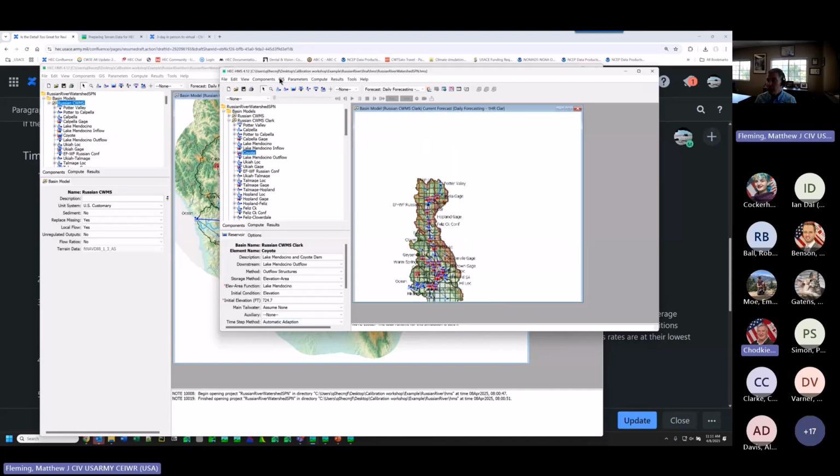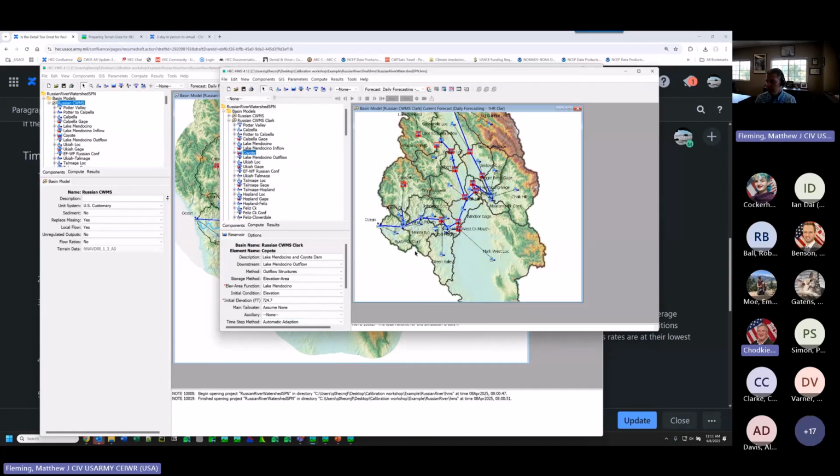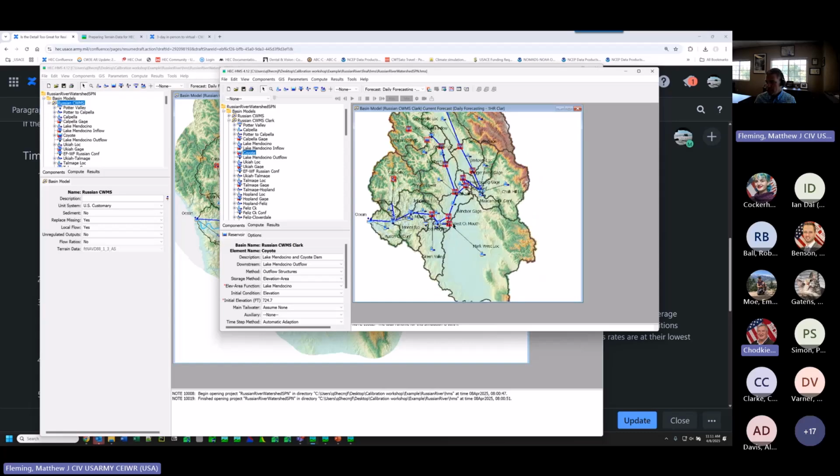This one, let me turn off the grid as well. Okay, and now you see in this model, there's just one subbasin representing that Mark West Creek. For this approach, it's definitely going to run a little bit faster because HMS is not performing the calculations for each of those individual elements. It's only running the simulation for this one subbasin right here. Precipitation is being varied spatially because we're using the structured discretization and Modified Clark transform. So we are getting that spatial variability. We're just not breaking it down into smaller subbasins. Okay. Any concerns or any additional thoughts about that approach?